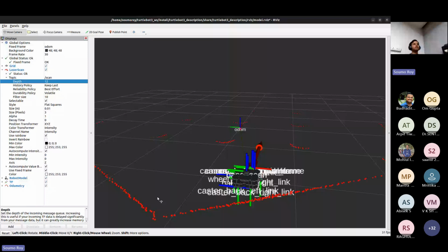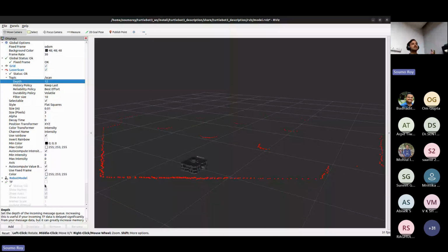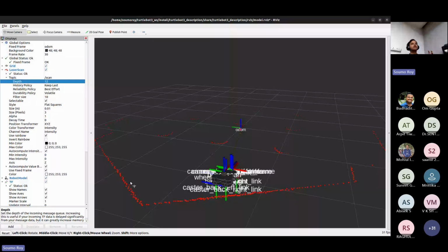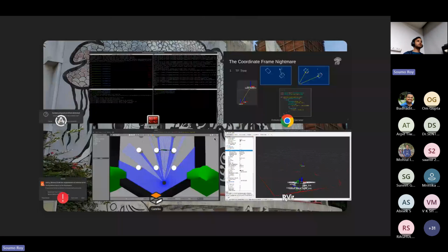Also, the odometry data you would ideally get from an IMU sensor present on the robot. So I will just click this to enable it. Now here I can also disable transformations to just show you that this is the robot, and now we want to know where the robot is corresponding to this world. And this is where transformations and odometry come in with a very important role to play, where you know where the particular robot is in a particular frame. So that's more about this. We will come back to our slides.